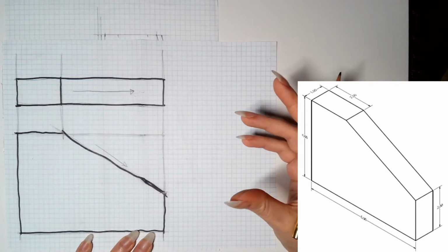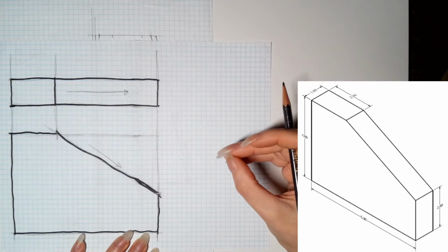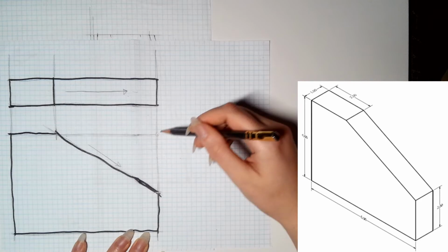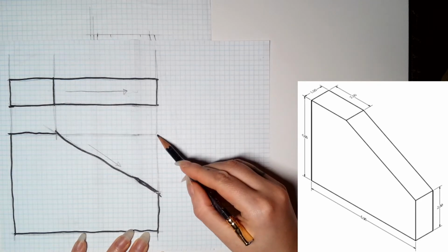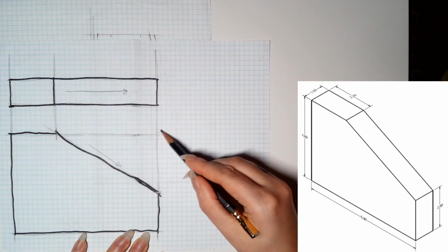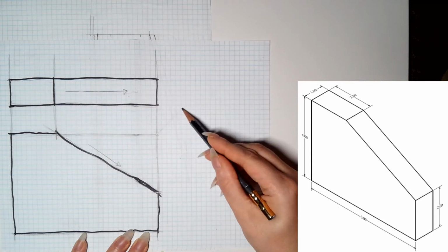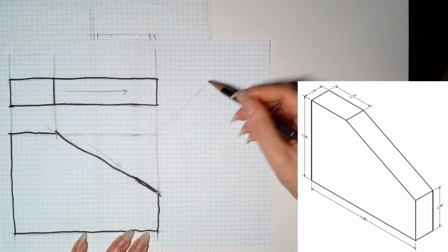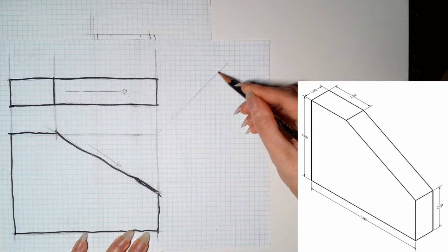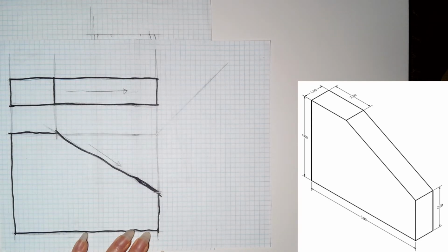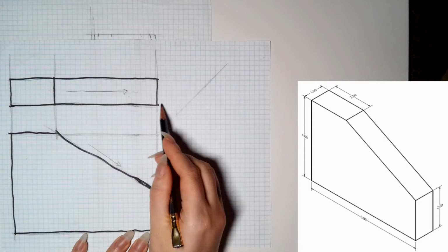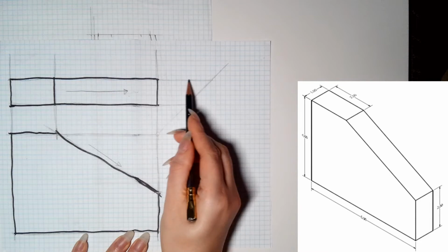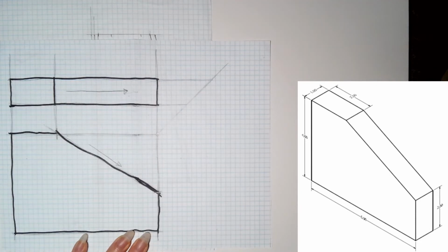So this again would also be a scenario where having my set square and my T-square would be ideal to just project that out. But since I'm using a piece of graph paper, all I'm going to do is draw a line that goes through the diagonals of these boxes, because that's also 45 degrees since these are perfect squares on graph paper. And I'm just going to go 45 degrees out, and then I'm going to project these edges over to meet that 45-degree line.